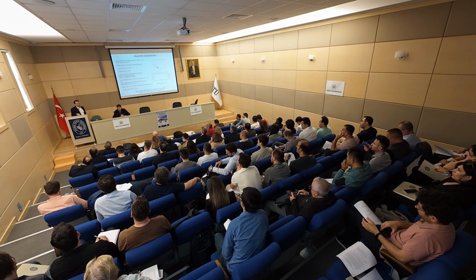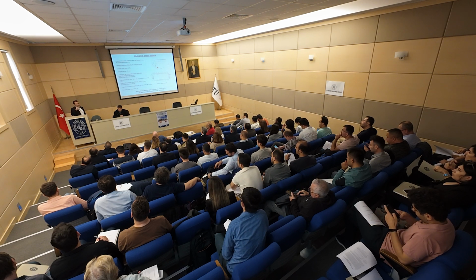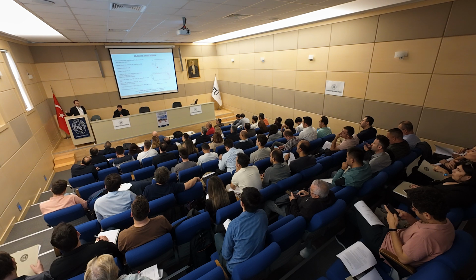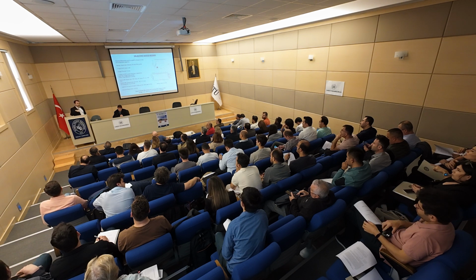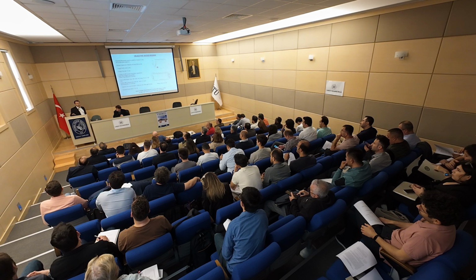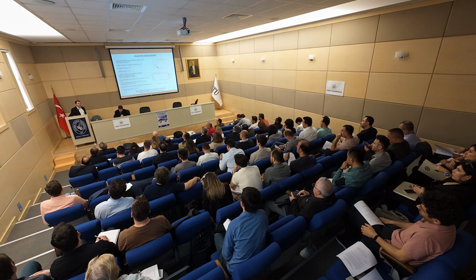Maybe one of the reasons that this works well is because we do have the 20 centimeter post-tension slabs as part of our design. But in the design process, we would have to check and detail the diaphragm as well. But this diaphragm would work in terms of the dimensions that we have here.